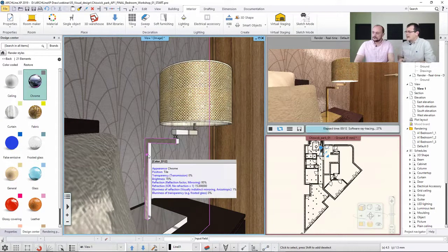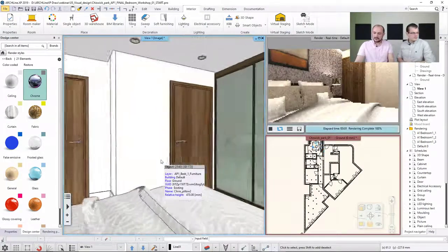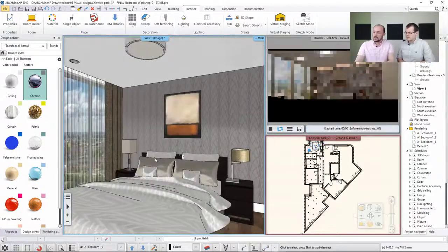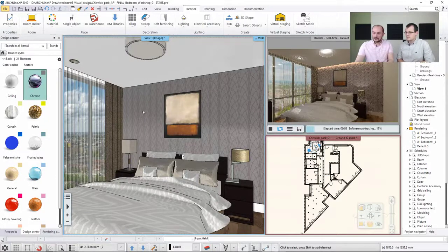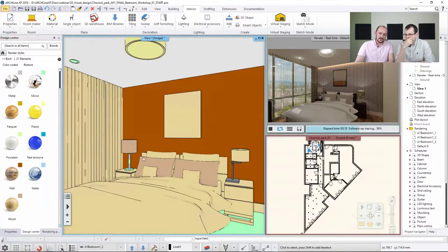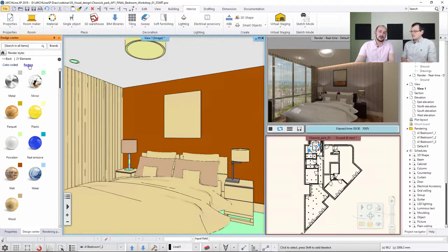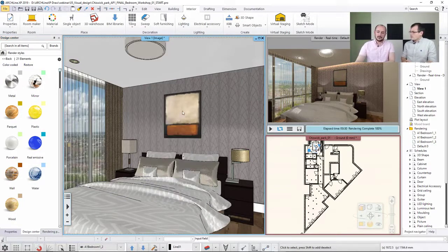How can I keep track of the styles that I have already applied? Well, it's an easy thing. Let me just zoom out and find this original view where we left off, and it was this one. So how to determine whether I worked with these or not? I just click on the color code and I can see whether those things are already set up or not. This color tone tells me that, for example, this item here, as you remember, I told that this should be a wall. So I can see the same exact color tone here. This helps me figure out whether I should work a little bit more on those or not. And if yes, then I can just click and drag and change it. When I click here on restore, it restores the original view and then it looks like this.